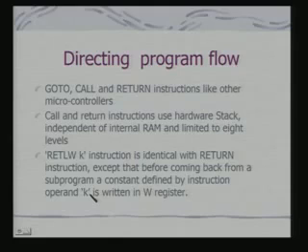So you are returning a particular value from the subroutine call using a single instruction. This instruction enables you to return a value in the W register, and this leads to very interesting tricks that you can play with your code, and we shall see such examples now.